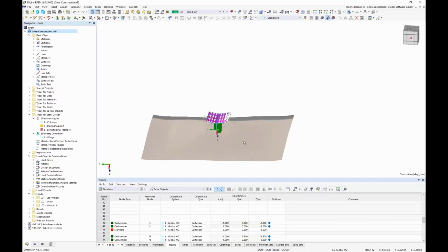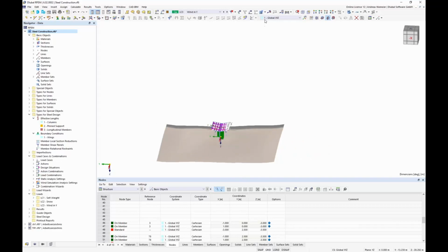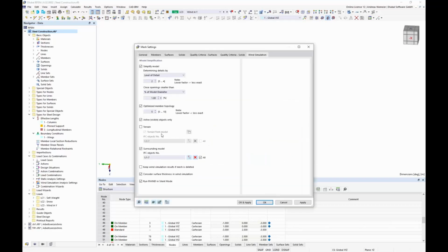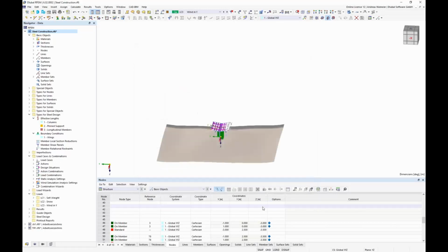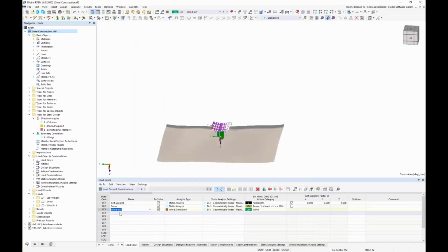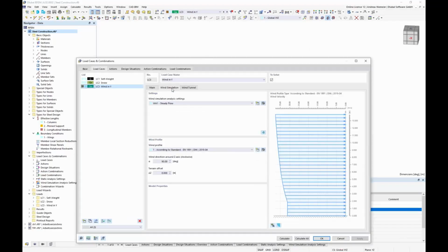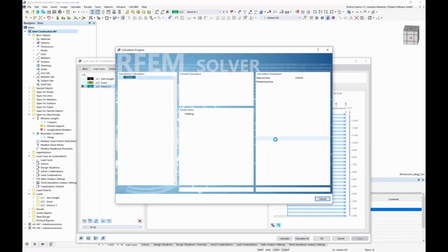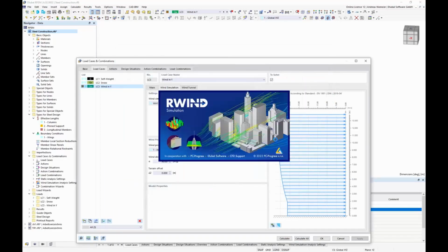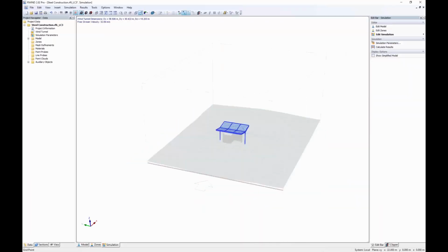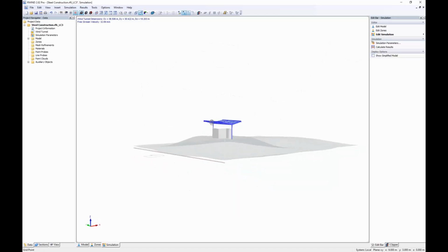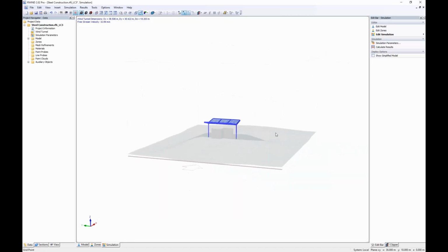And if you say now in the mesh settings, wind simulations, terrain, no IFC objects, only from model, then the interface knows when it transfers data to the wind tunnel, even the terrain should be considered. What helps? Because now we have the tools to make batch processes for different wind directions. What brings me to the next point.